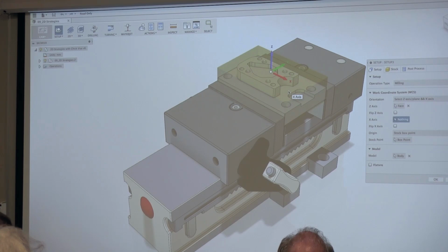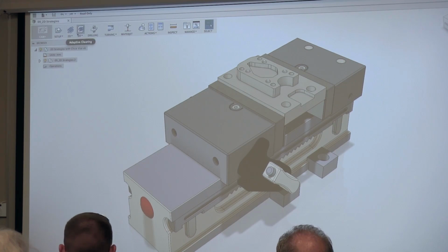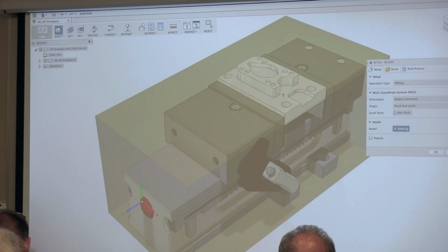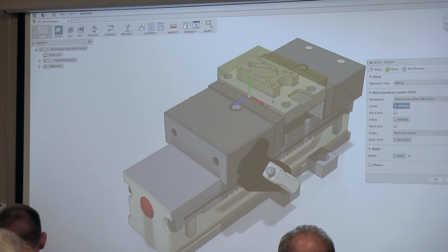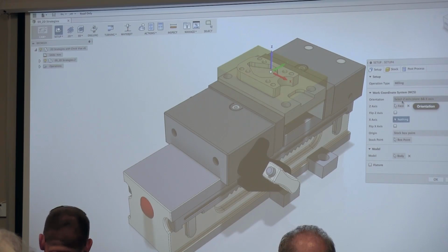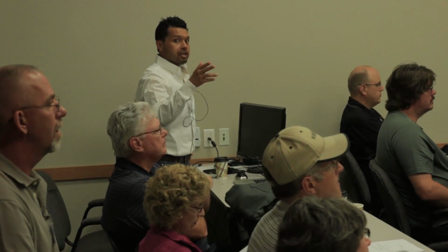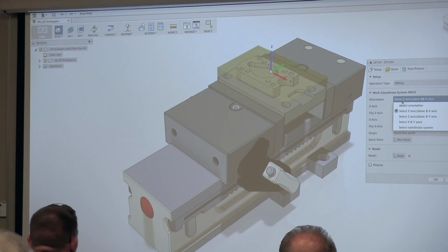So I showed you two different ways of doing this. So once again, it depends which way is easier for you. Now personally, me coming in and picking this face, this part, and saying, let me just pick the stem and then this face, it's quicker for me. Or you can come down here and pick the Z axis plane and then click that top face and then orientate it there. So please go ahead and do that if you haven't done so.